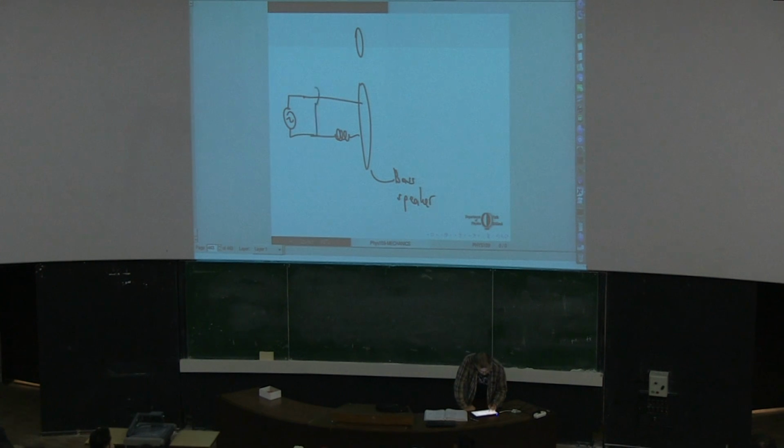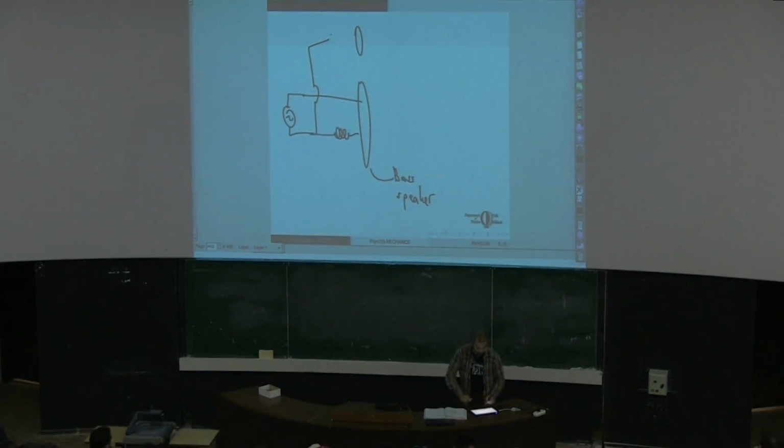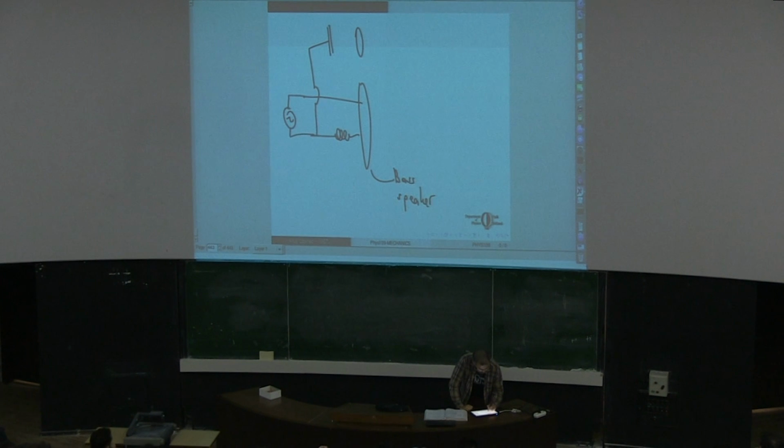And then you want the large frequencies to go to the small speaker, not the low frequencies. So you attach it through a capacitor.